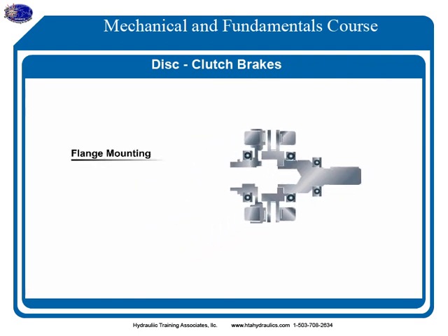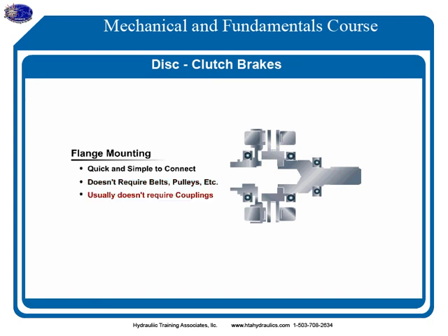Flange mounting has become popular because it is quick and simple to connect. It does not require belts, pulleys, etc., and usually does not require couplings. It is usually compatible with NEMA C-faced motors and gearboxes.